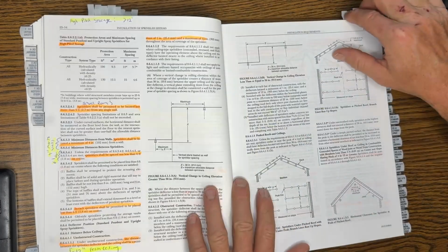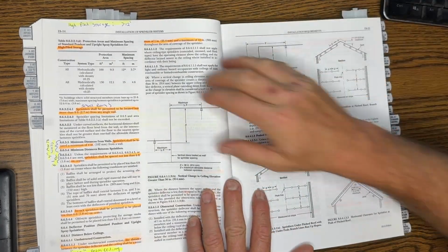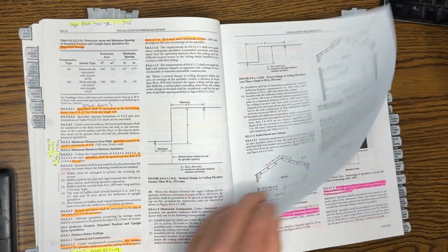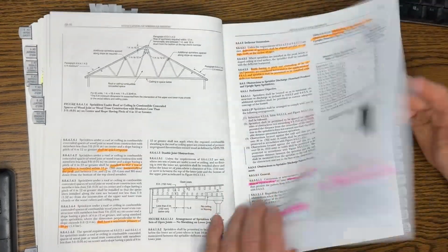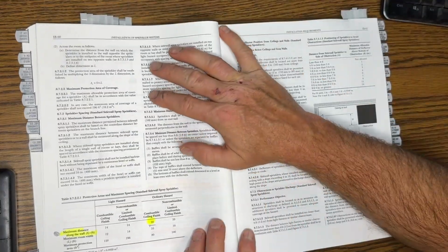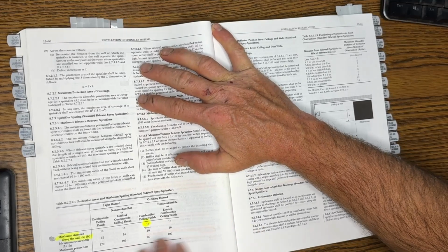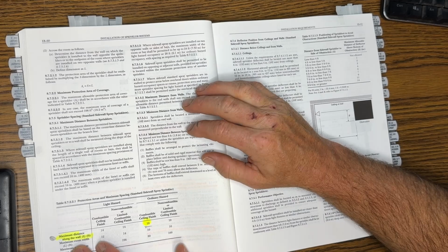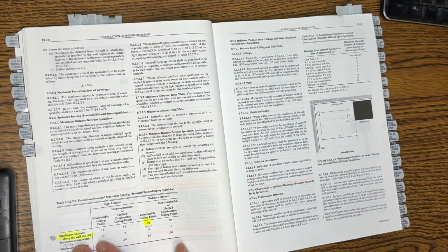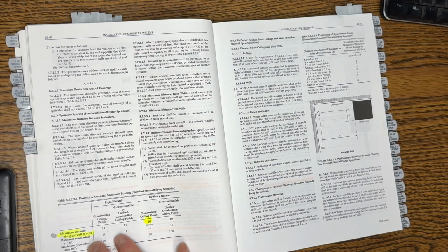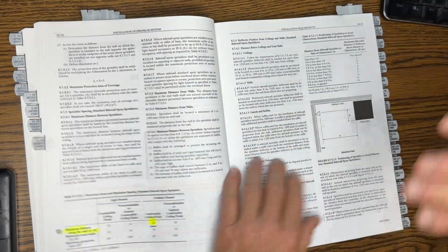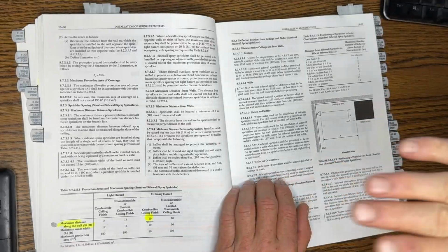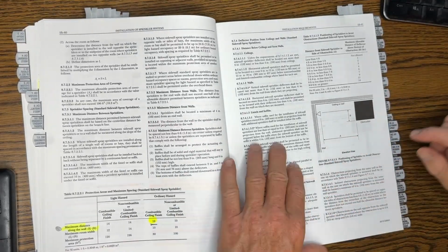All right, let's zip through this. I don't want to kill you. There's a lot of good stuff here, but if you're not familiar with fire-related stuff, this is brand new. How the heck would you pass this? It's not easy stuff. So this question here, 8.7.2.2.1, what is the maximum spacing along a wall in an ordinary hazard design that sidewall sprinklers can be spaced? 10 feet. Sidewalls are the ones that come through a wall instead of through a ceiling. They're in a wall and they spray out.